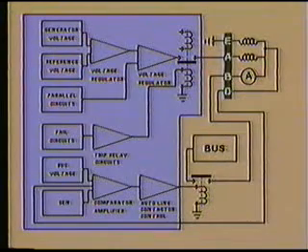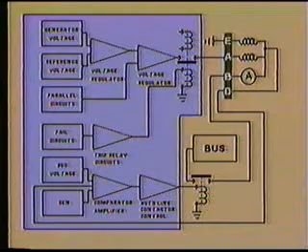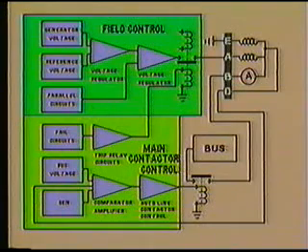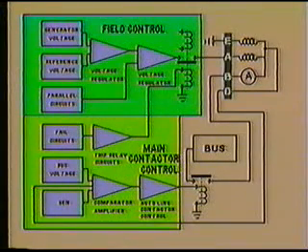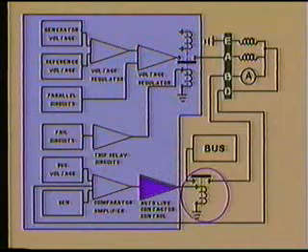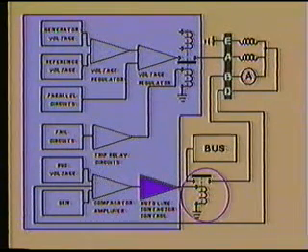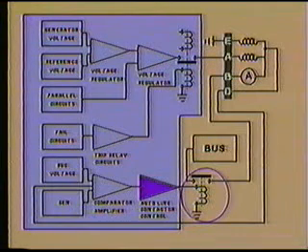Before we begin our detailed discussion of the internal workings of the generator control panel, let's consider its operation from a function standpoint. The control panel performs two major functions in the generator circuit: controlling the current supplied to the field and controlling the closure of the main contactor relay. The main contactor relay coil receives power from an auto line contactor amplifier circuit within the control panel.